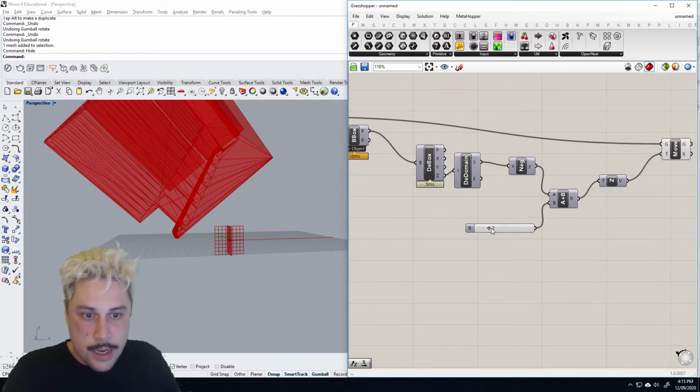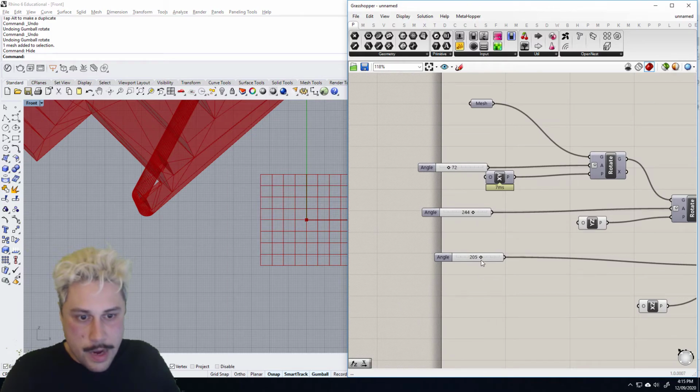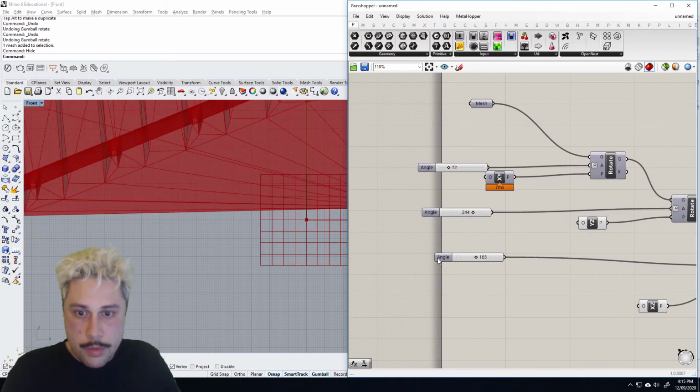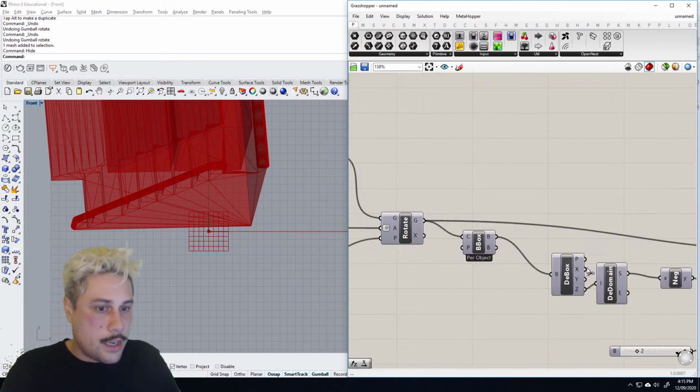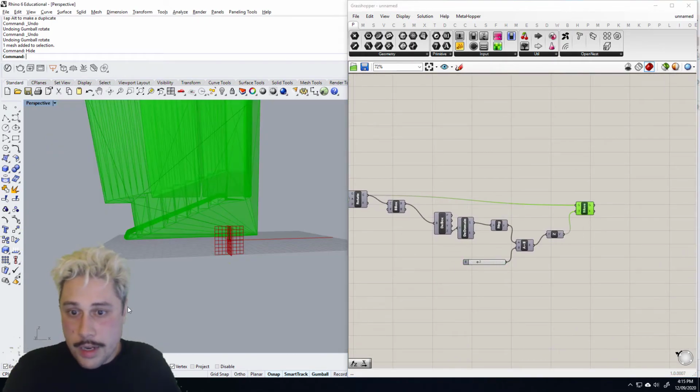But we've raised it up 2 or 3 mil, because generally when you've got a raft that sits underneath your 3D print. Can we orient this back down a bit more? There you go. So it's going to be sitting 2 millimeters above 0. Great.